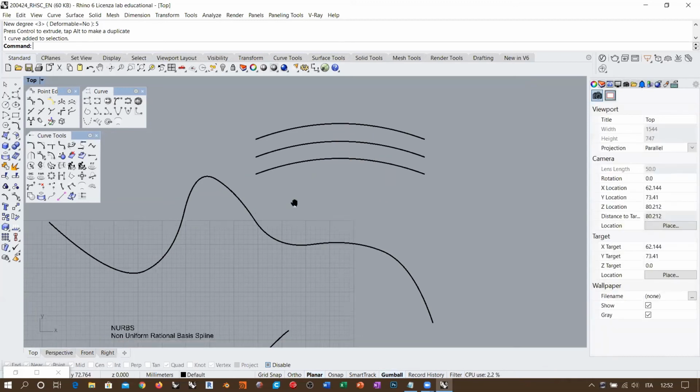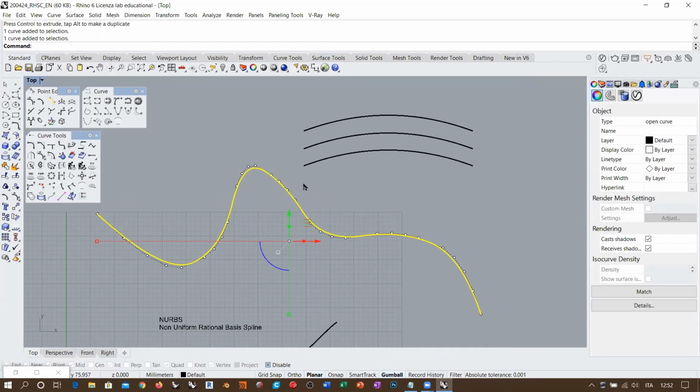So if I want to change the shape of a curve more smoothly, I don't increase the degree. I decrease the degree. Because if I decrease the degree, one control point will affect a larger portion of the curve. If I increase the degree, I don't change the shape, which, from an intuitive point of view, is what any designer would do. I want to increase complexity without changing the shape of the curve.